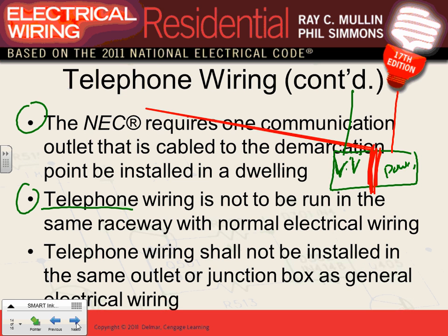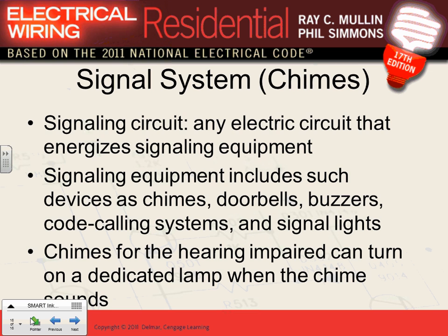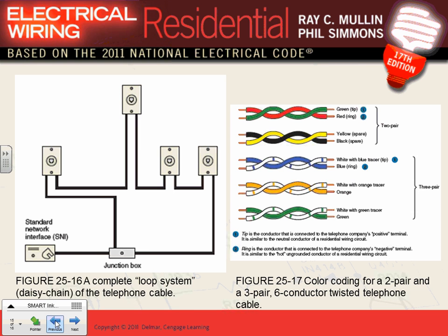Okay. So everybody's okay with that one. If I test you, an example: separated by 12 inches, that's if they're underground in a trench, 12 inches. If they're separated wires, 2 inches. But these are inside a box.